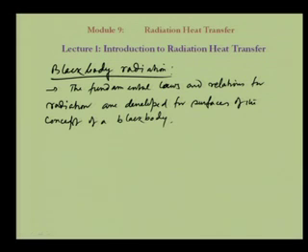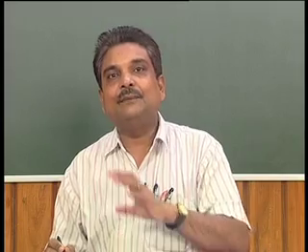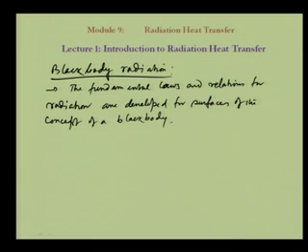as I told you, like emissivity. A surface which is a black surface is designated to emit 100%, that means 1, whatever its emissive power, that will be 1. That is basically that emissivity is 1. So, all other surfaces will have emissivity lower than that, a fraction which will be less than 1. Now, what are the properties of a black body?